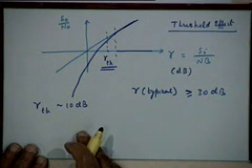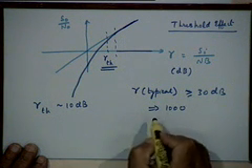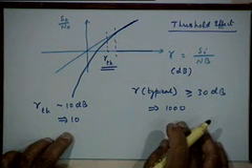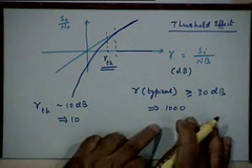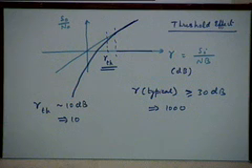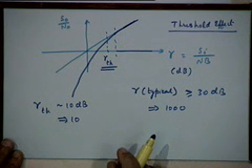So which is much more than this, because this in absolute terms is about 1000, and this in absolute terms is about 10. So since the typical values are going to be much larger than the threshold value, you will never see the threshold effect in typical radio receivers, because you are typically operating at input signal to noise ratios much larger than the threshold value at which this phenomenon will start to be seen.